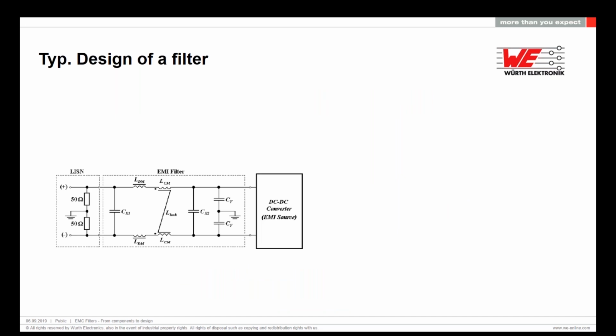When we take a look at an EMI filter, this is a basic example of one. In this construct, we have one common mode choke, two differential mode chokes, two X capacitors and two Y capacitors. But while designing a filter, we put a bunch of components together, and we need to know what they are filtering. So basically, we need to build the different models of our filter.